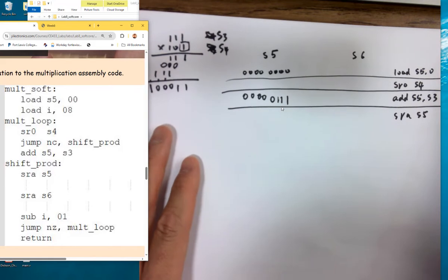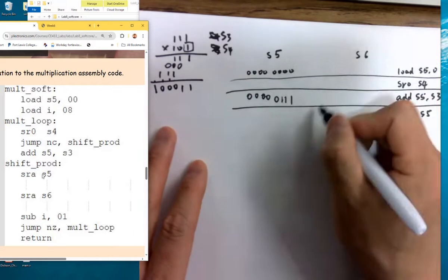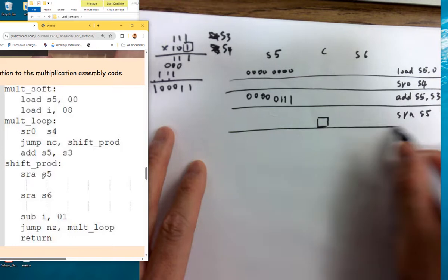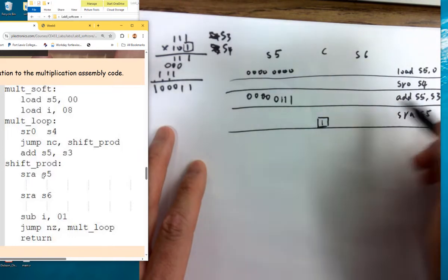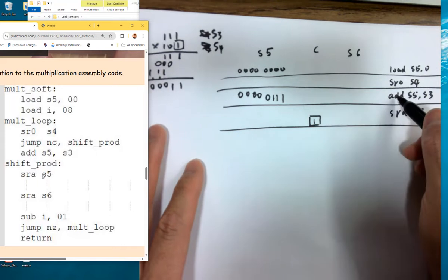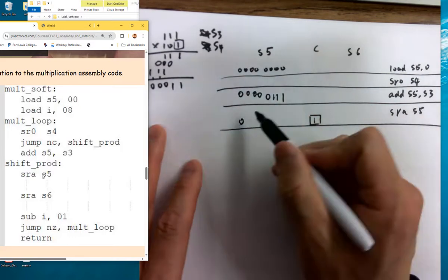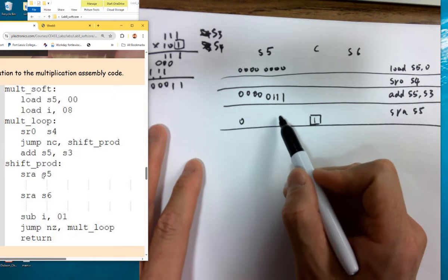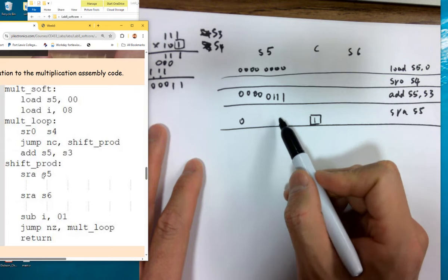So in that case, I'm shifting for this line of code, right? You've got a C bit in the middle. This instruction is shifting everything to the right, so this one goes to C, and the previous C after this line was what? I just told you. 0. Okay, so 0 will be put in the MSB of S5, and everything got shifted to the right. So how many zeros before we put 1s over here? Are we losing the MSB? No. So how many zeros? 5. Just count. 1, 2, 3, 4, 5.